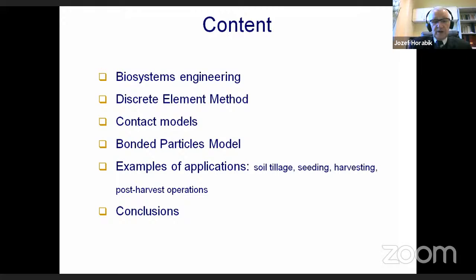The theory of adhesive Hertzian contact was formulated by Johnson, Kendall, and Roberts 50 years ago. For particles larger than a fraction of millimeter, the most important source of adhesion is a liquid bridge between particles. And for these bigger particles, the linear elastic plastic contact model with the linear cohesion is most frequently applied.